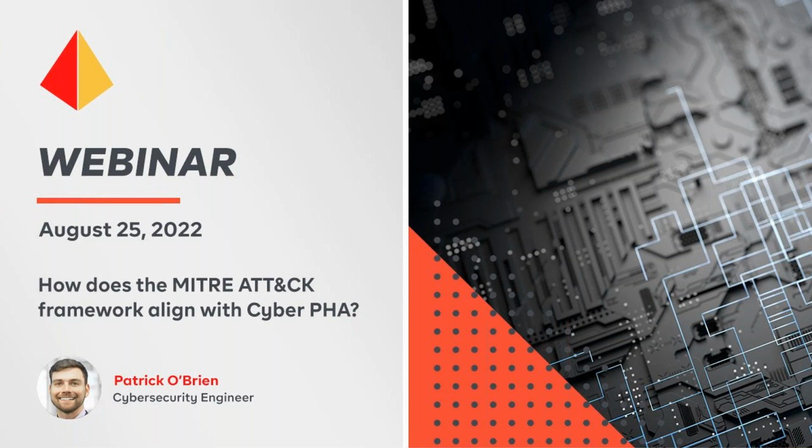So the first question I have here is, like the IEC 61511 safety lifecycle, is there a cybersecurity lifecycle in the standard? Yes, IEC 62443 does help outline a lifecycle-based approach, and we can think about lining it up with a similar assess phase, where you're doing your risk assessment, your implement and design phase, and then your operations and maintenance.